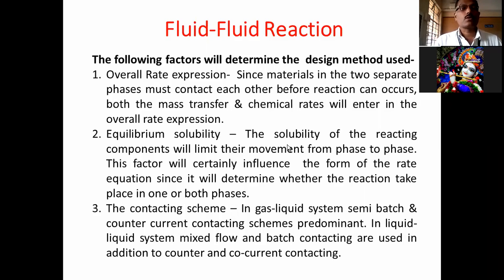So the rate depends on the equilibrium solubility. The equilibrium solubility occurs at the interface, where the gas film and liquid film meet. At the interface, the solute in the gas phase is in equilibrium with the solute in the liquid phase. So the rate depends on the equilibrium solubility, and this is important.